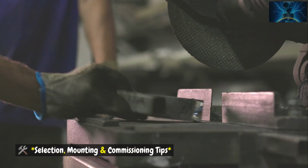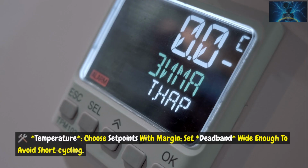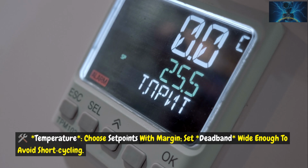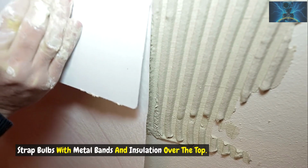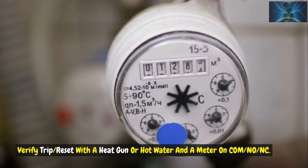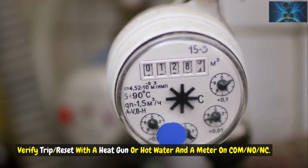Selection, mounting, and commissioning tips. Temperature: choose set points with margin. Set deadband wide enough to avoid short cycling. Strap bulbs with metal bands and insulation over the top. Verify trip or reset with a heat gun or hot water and a meter on COM, NO, NC.